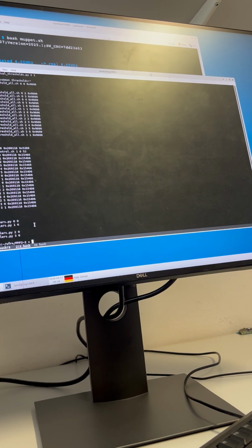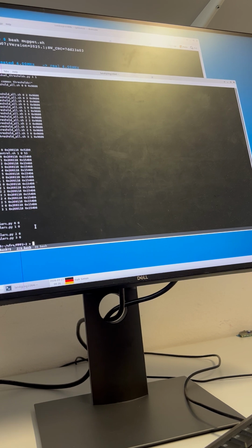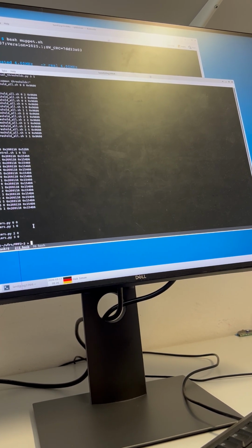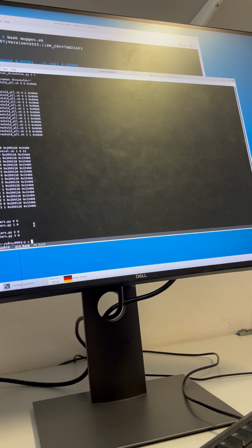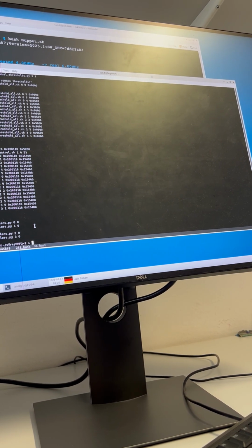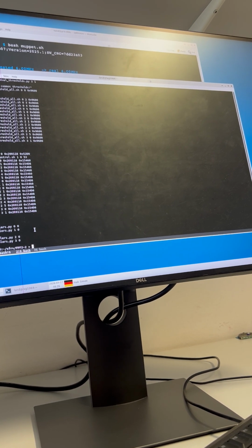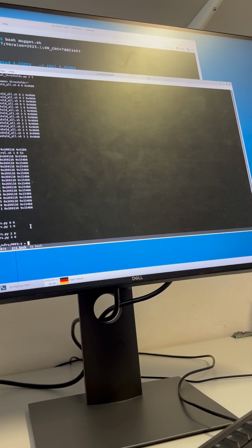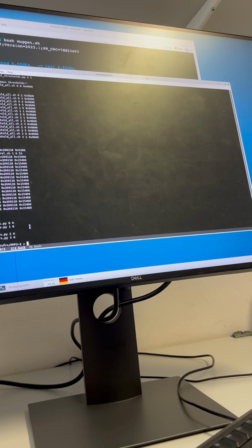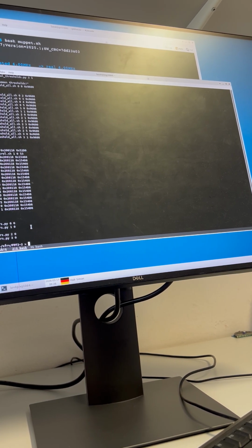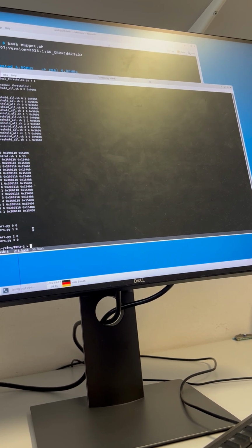For the analysis of data, of course, one can do the full analysis, because we can make cuts on the times and on time over threshold, and do the fitting of the position, the full story. But for online, this might be much simpler: just look for channels up and down. Of course you have noisy channels up and noisy channels down, but the coincidence is very powerful. Right now I have, I think, better than 100 kilo events per second.